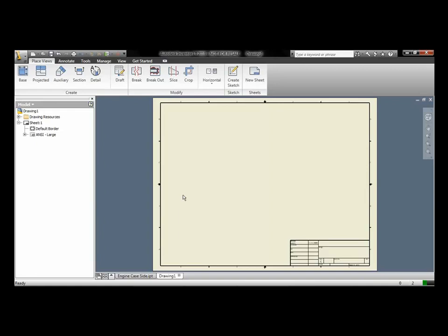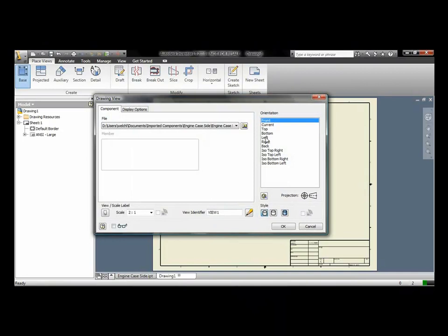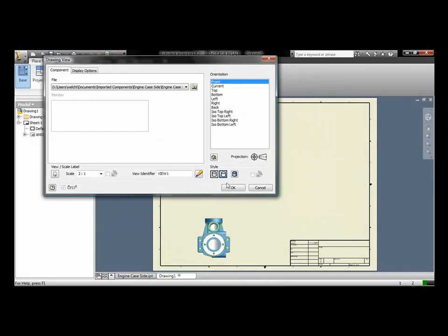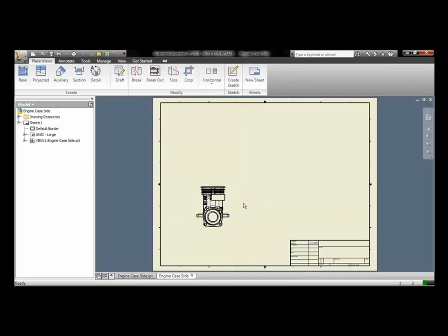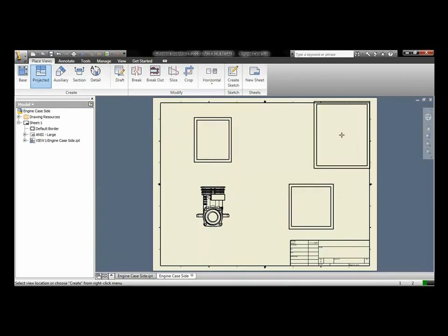So leveraging the power of DWG inside of Inventor LT, we can now go ahead and document not only any features that we created on this model, but any views that we need for manufacturing. Now, again, this is a fairly complex model, and from a 2D user, think of all the detail they would not put in these views, all of the fillets, some of the hidden geometry, and certainly not an isometric view.